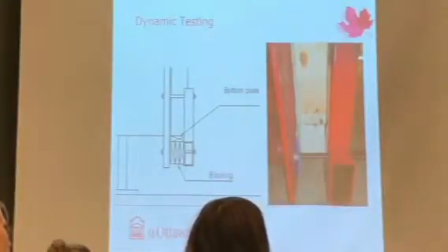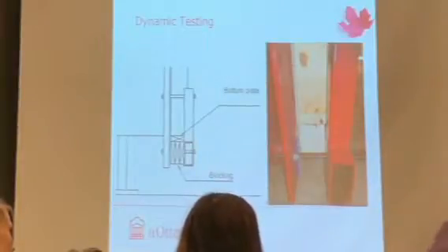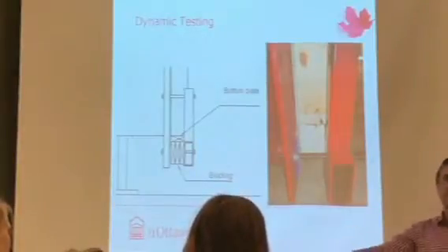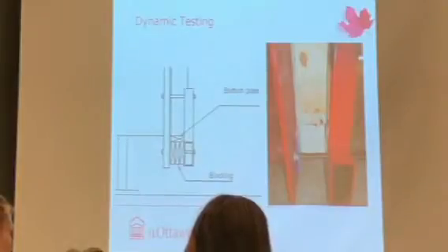So very, very weak, if you will, right? But you put enough of them in there. We have a provision in Canada that says if you put a nail every 150 millimeters, then you should be able to take forces in plane for seismic load, in plane of that wall, that's sufficient enough. Okay, we said, let's do this and see if it works for a blast design.